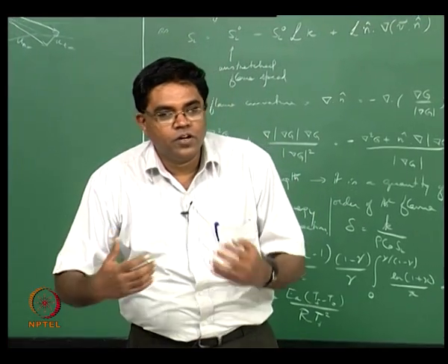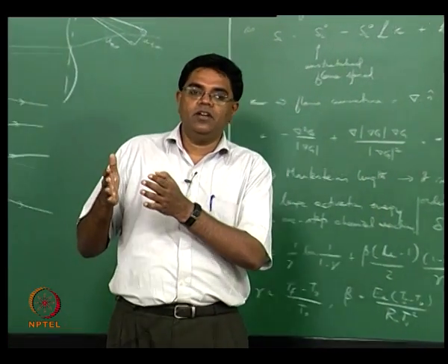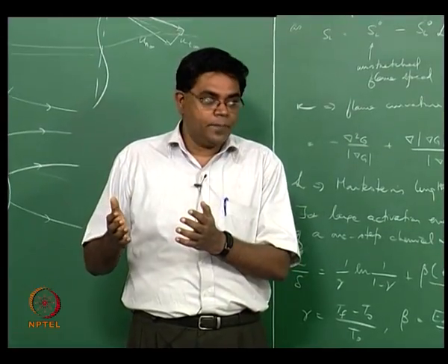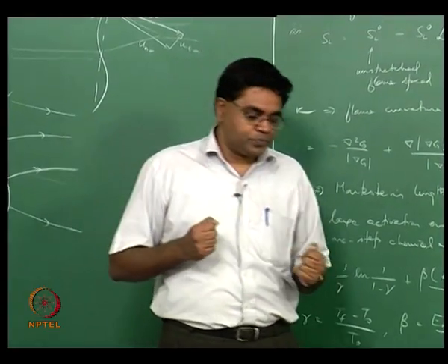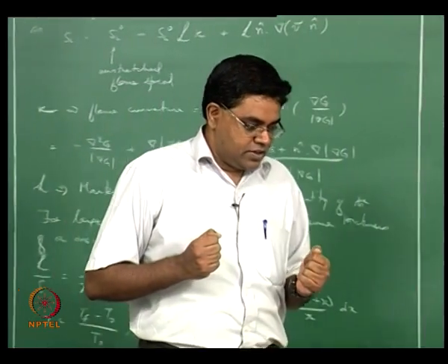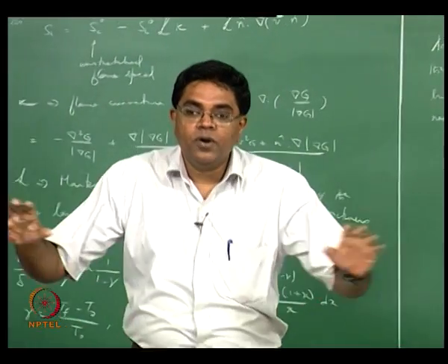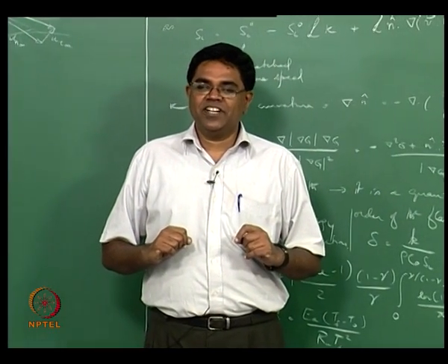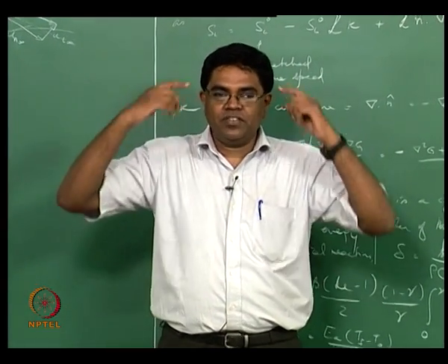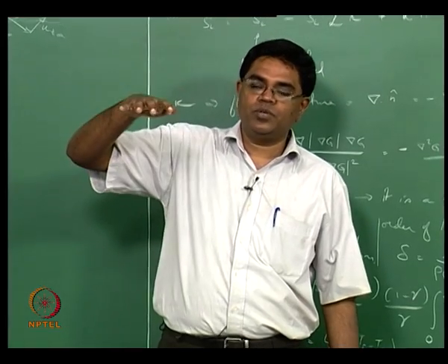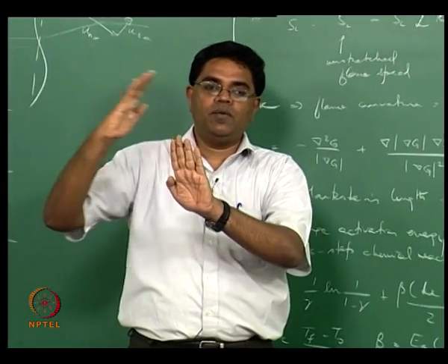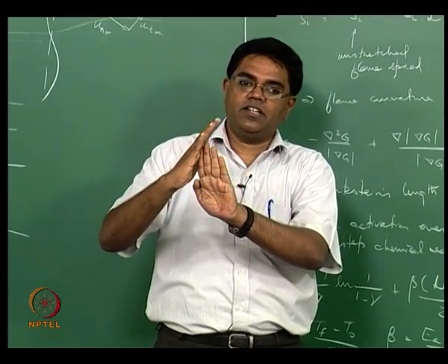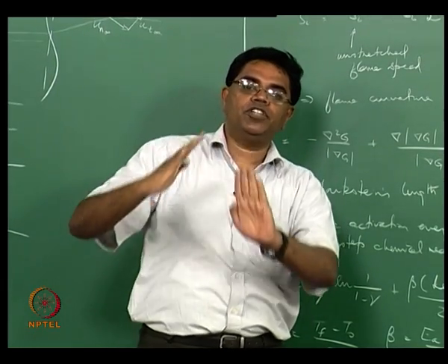So we need to focus a little more on what's happening near the base and see what the fate of the flame speed is as we approach the base, as well as the flow, which isn't uniform either. We tend to think that you have a uniform flow approaching the flame, and a uniform flame with a constant flame speed with which the flame attacks the reactant flow, and therefore you have a shape.